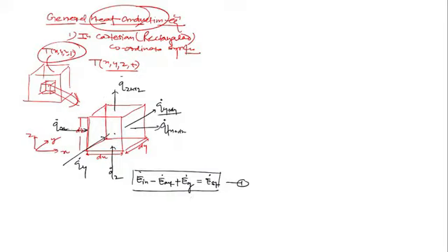Now there must be some energy source. So here E generation is there, and also there is heat stored. Energy gets stored in this system only. So how can we find the energy generation? E dot generation is from the uniform heat source. The heat source generates energy as a uniform heat generation per unit volume. So let's say q dot g.